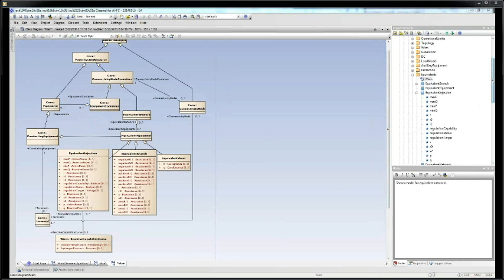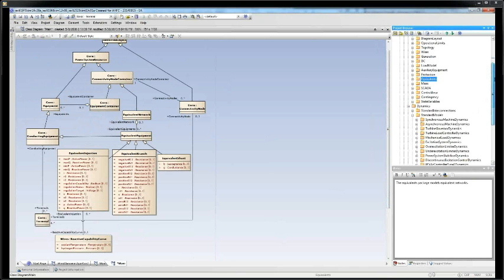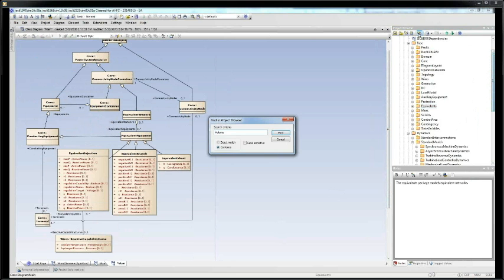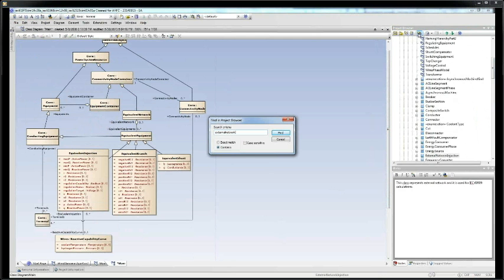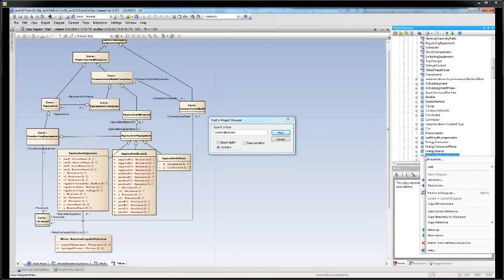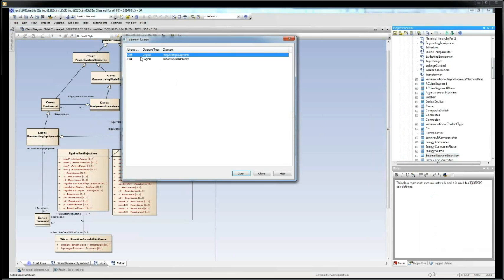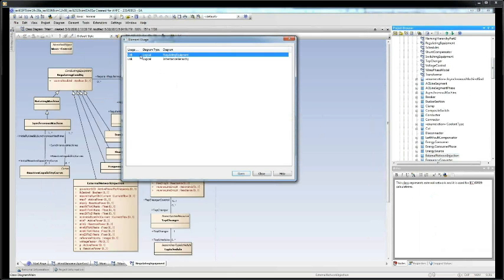All right. I tell you what, Jay, since you're on the line. I found it. It's actually called an external network injection. It's a class with similar connection capability as any other piece of equipment. At that point, you can define the available fault with all its X and R ratios at a specific boundary. So you can define these at each boundary location of your network.